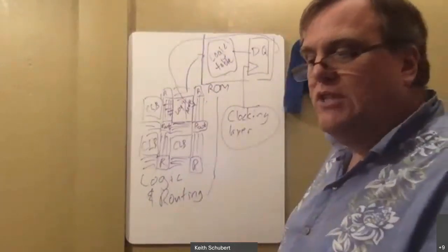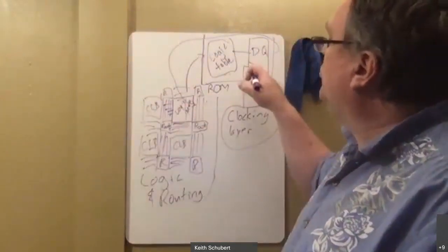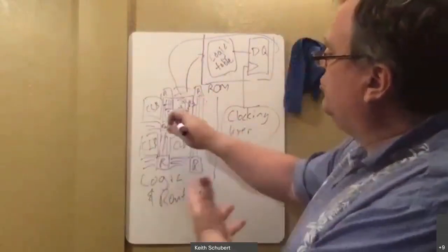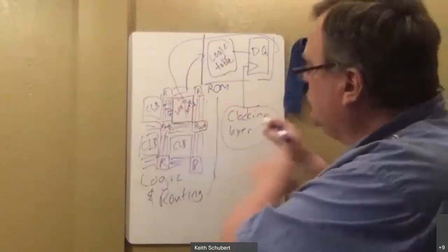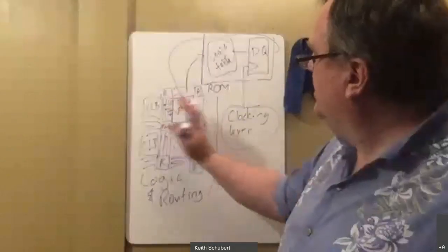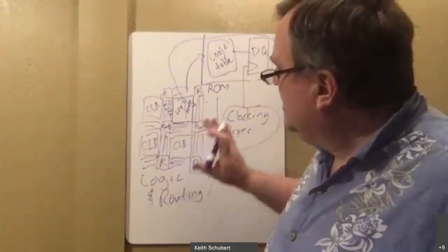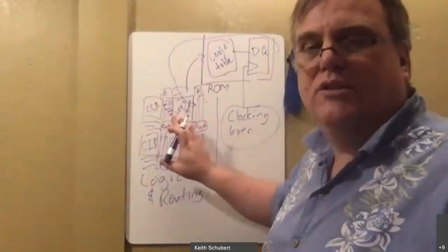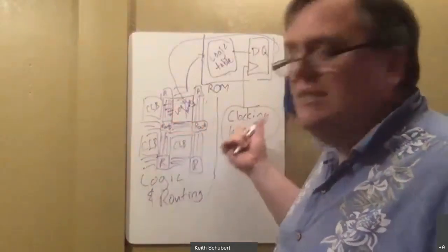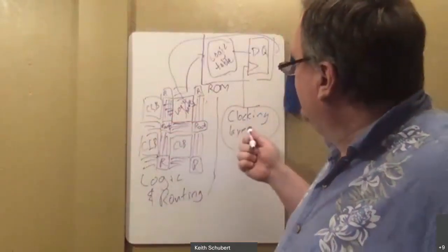So now imagine for a sec, you take a logic signal, something you generate here, but you try to input it to a clock. There's no way to route this signal to the clocking layer. You see the separation between them? And the reason is the system doesn't know how to time this. Well, it knows how to time it as a logic signal. It can't time it precisely as a clock. So therefore, it doesn't want you to take these and put them over here.